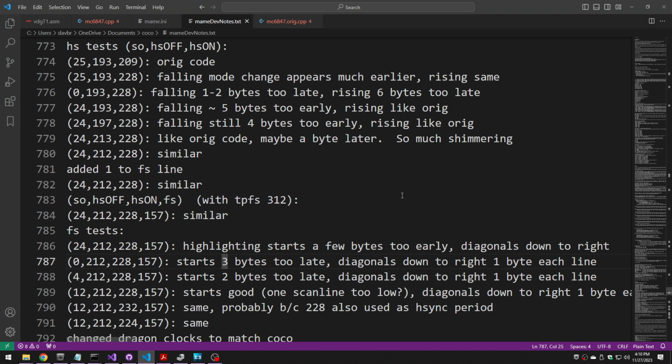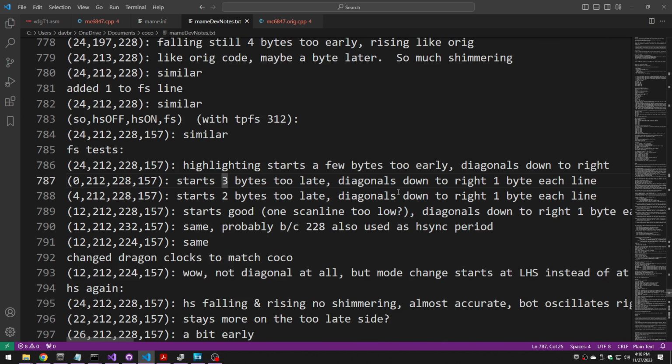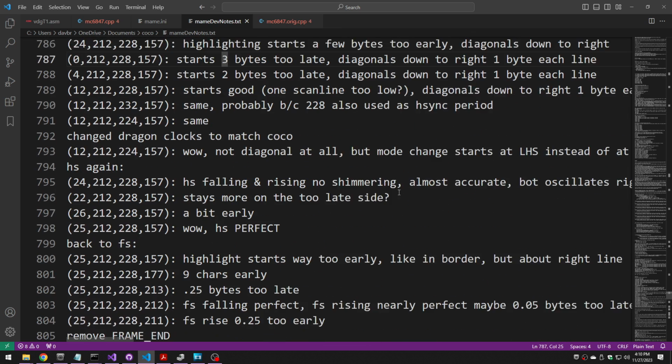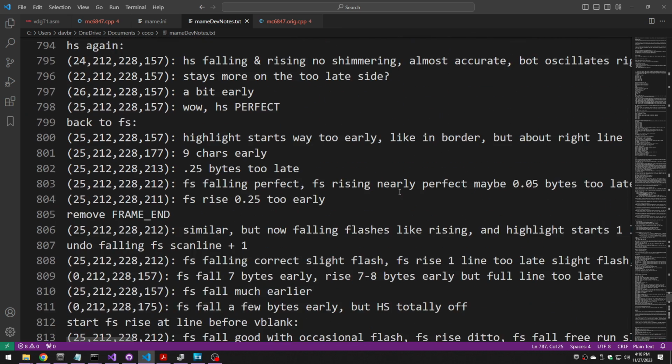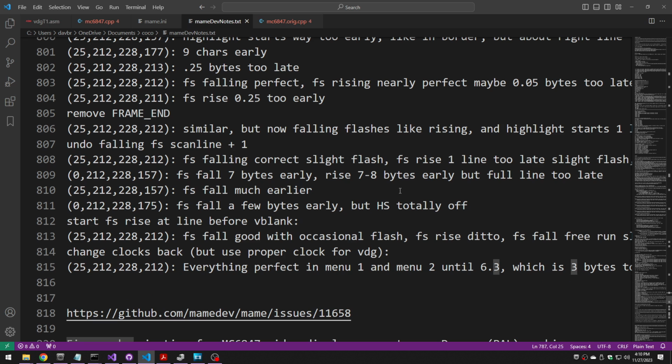But after making those changes, all the tuning I had done prior to the H-sync on and off and the horizontal offsets before rendering needed to be tweaked again, because they were tuned to some of the incorrect other parameters. Now that I made those parameters a little better, it was more trial and error. I was going out of my freaking mind trying to get things correct.